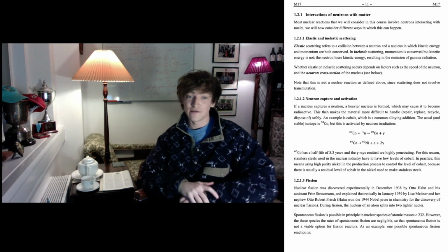Well, the problem of cobalt in nuclear materials is because cobalt-60 has a half-life of 5.3 years, so it tends to stick around. And gamma rays are highly penetrating, meaning that if you've got cobalt in your materials, they're going to be very difficult to work with once they've been activated or irradiated, as they're going to harm workers in the proximity, because gamma rays are very harmful to biological material, and so you're not going to want to go near these.